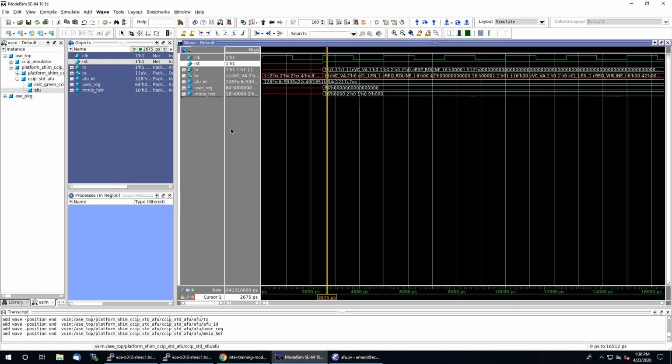All right, so trying to find that just by manually scrolling through the bottom here would probably take a very long time. So what we can do is exploit knowledge of how we know when a memory mapped read is occurring.